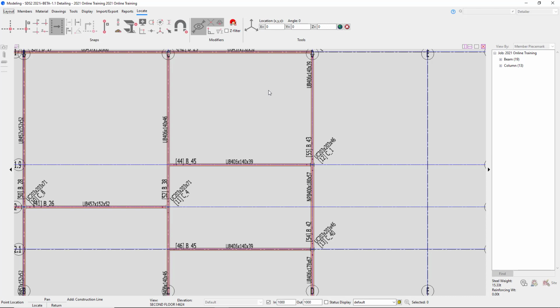And if we refer to our sheet S1, we can see that in that bay there, we have a couple different dimensions that are being called out. And those are the dimensions I'm going to use to get my construction lines in. So I'm going to start from grid line D and work my way to the left. So we can see that that first dimension we have there is at 914 millimeters, and that'll be to the left side of D.